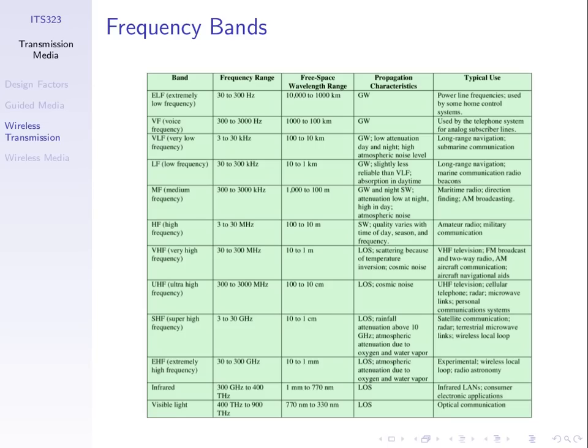In some cases, in some systems with satellite TV, which uses frequencies in the order of, in this super high frequency range or band, in the order of 10 gigahertz, frequencies in this range are attenuated by the atmosphere and water vapor, for example. So when it's raining, the signal from the satellite comes down to your home and the receiver, and the signal needs to go through the rain, the water in the atmosphere.